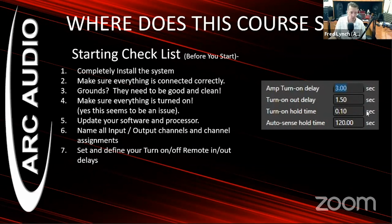Or if you're running multiple processors, you run it in chain of this as well, and you can run that on the output of the first DSP. Turn on hold time is in regards to how long you want the internal muting circuit in the processor to stay turned on when you're shutting off your system in order to prevent turn off pop.